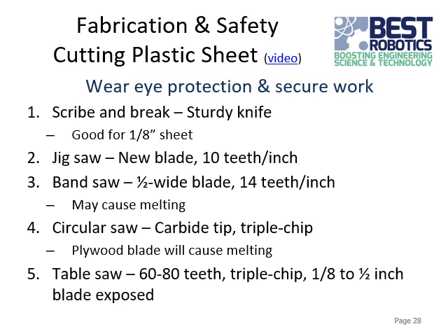And then also make sure that you're securing your work. Don't try to cut something while it's loose and flopping around. Clamp it down to a sturdy surface, or put it in a vise or something to hold it steady.